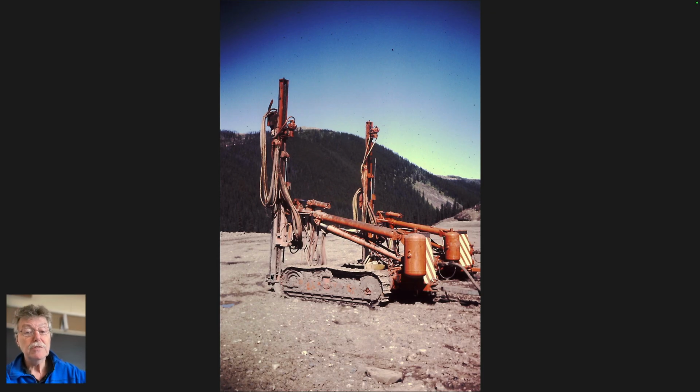And so it will make holes which are probably a few inches in diameter, and there you can add multiple lengths of steel to this to go down 20, 30, 40, 50 feet, I would imagine. And then typically for these, you don't take samples, you don't log the chips that come out, because all you're interested in doing here is making a hole which you'll then put ANFO, ammonium nitrate fuel oil, mixture in as explosive, put a detonator in it, put stemming at the top to keep the generated gases locked in, and use it for blasting a bench in an open pit mine.